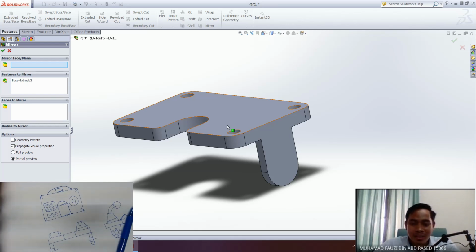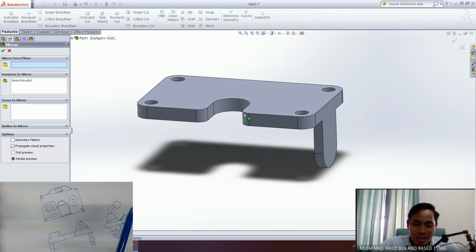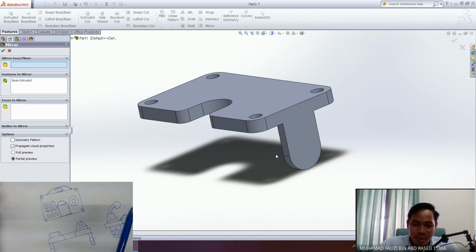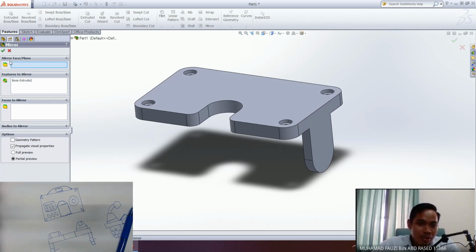When you see a mirror, you can see your face, right? So it's the same here. Whenever you put a mirror at any position for this part, the same figure will also appear for this part. So you need to select the position of the mirror. Here we have the mirror face plane. This is where you want to place the mirror.